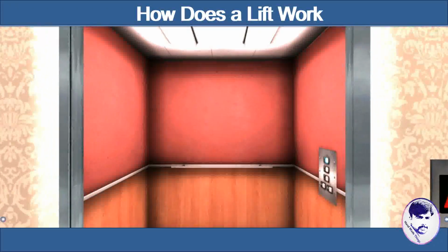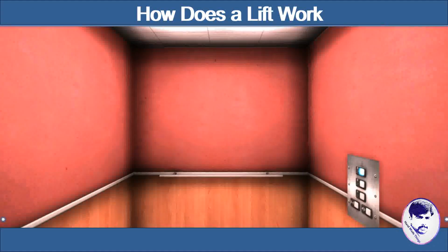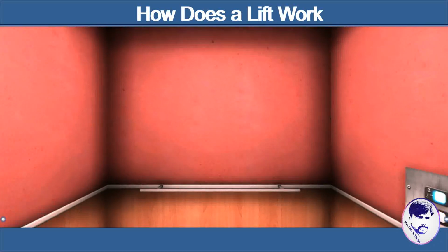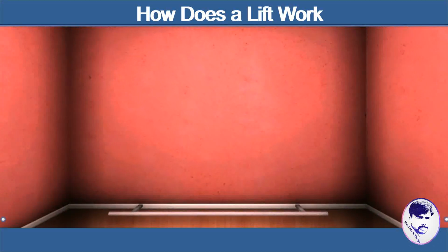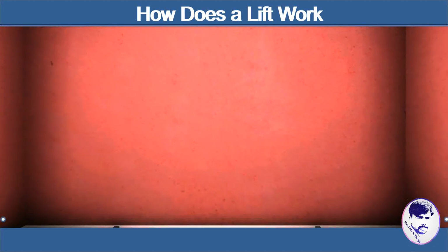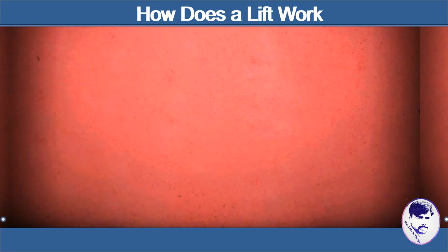Lifts are also equipped with electromagnetic brakes, which become active when stopping at a floor. The brakes are held in an open position by the electromagnets. This way, they automatically close in the event of a power outage. If the cabin plummeted in spite of all these safety features, a buffer at the bottom of the shaft would cushion the impact.